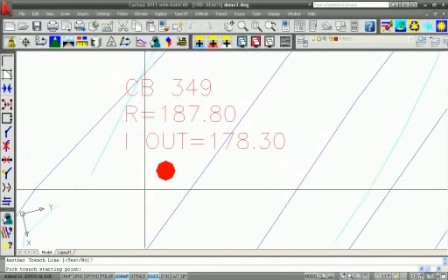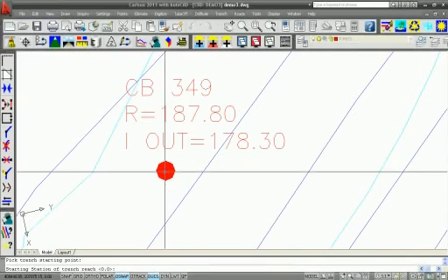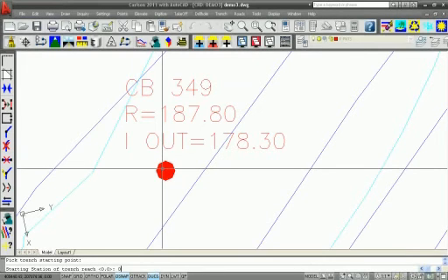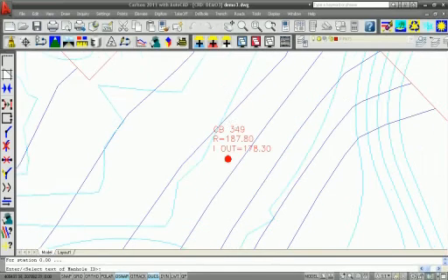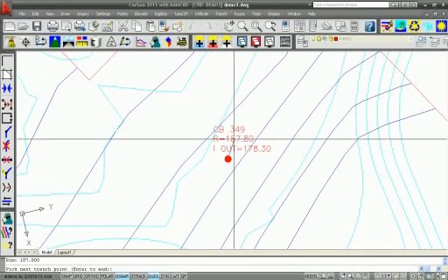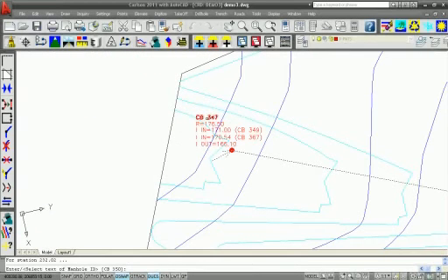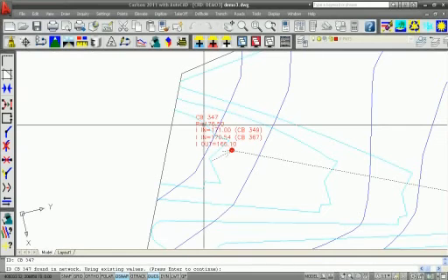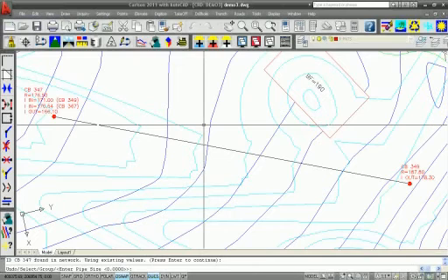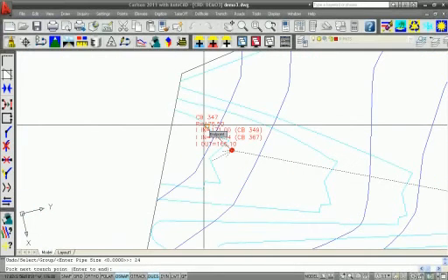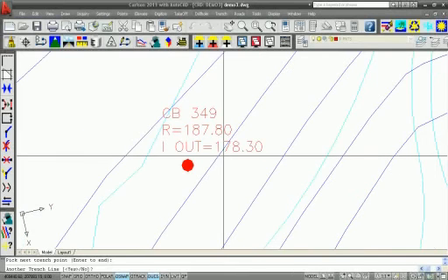and we have one more down here. And just pick this point. Starting station 0 on this as well. Manhole ID, the invert out and invert in, same. Rim elevation, and then I'm going to connect back up over here. Okay. And it's going to use those existing values. Pipe size, let's call this one 24 as well. Okay, select another one. No.